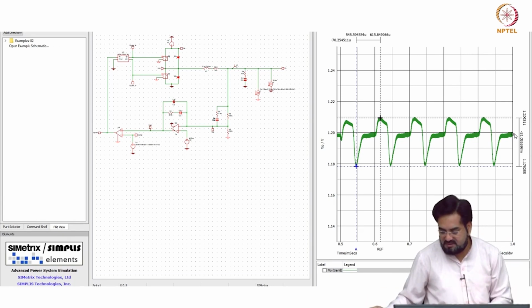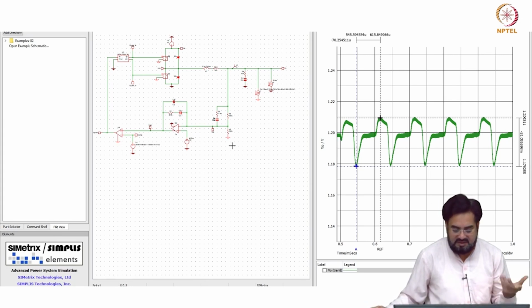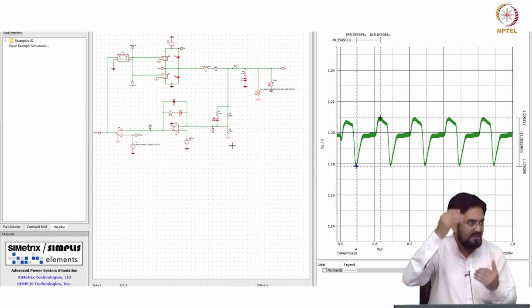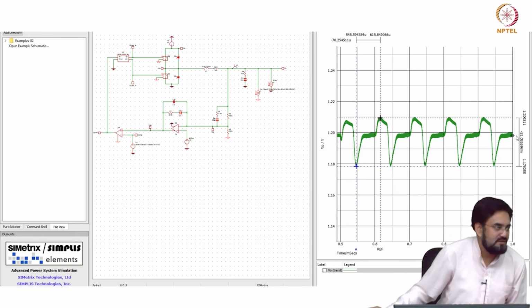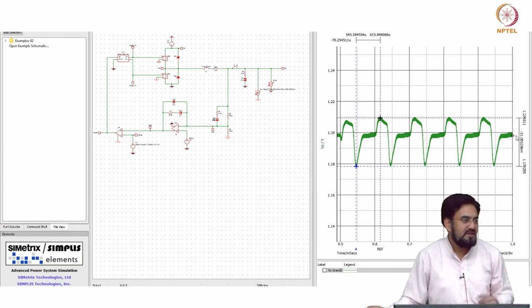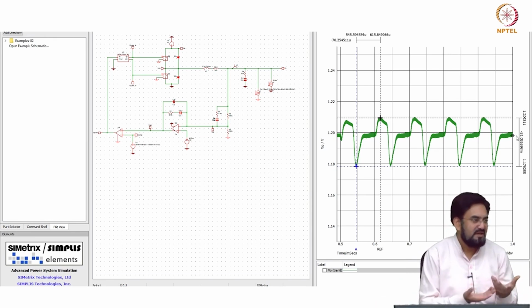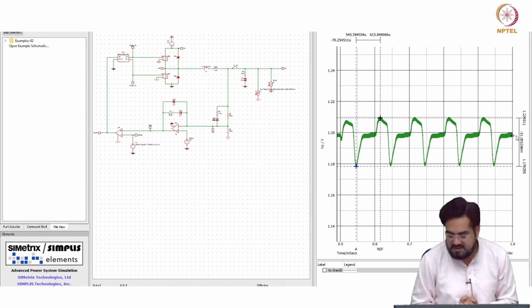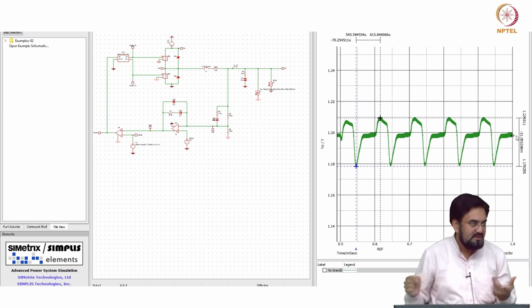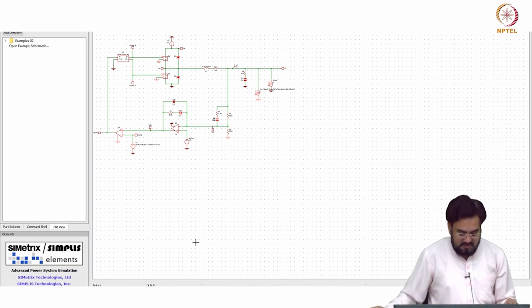So you get significant suppression by adding those poles. We were looking at roughly 8 to 10 times if you looked at the gain. So after adding these poles, this may be less than 5 millivolt or so, and your ripple spec usually remains 10 millivolt or less. So as long as you have anything below that, it may not affect that much, but if you have a larger ripple, then it may affect your system. Okay.